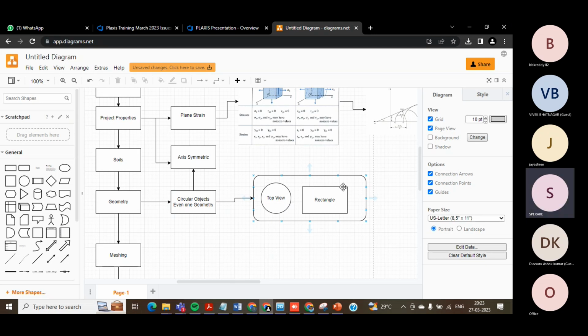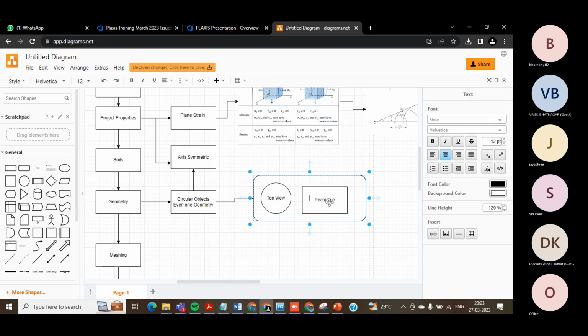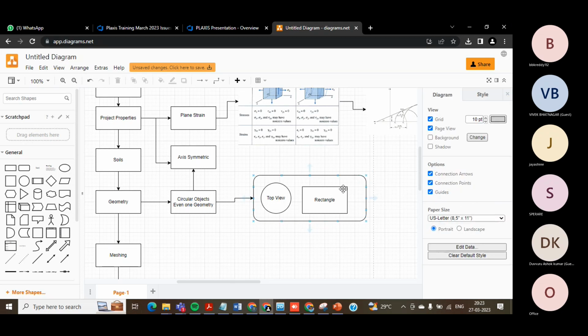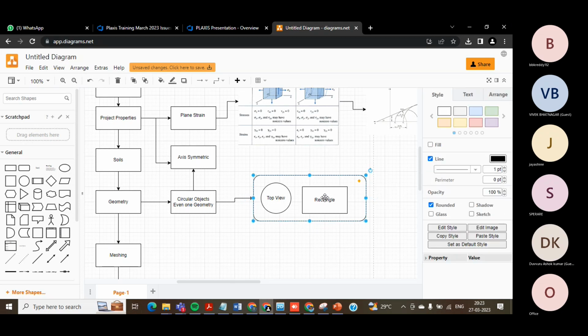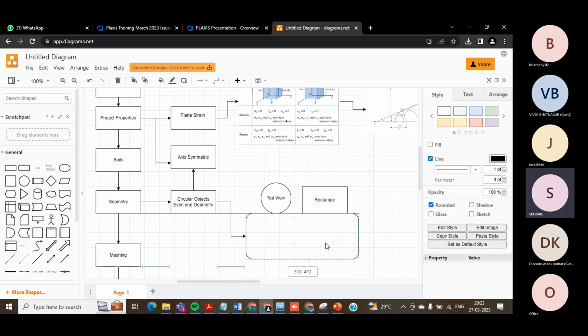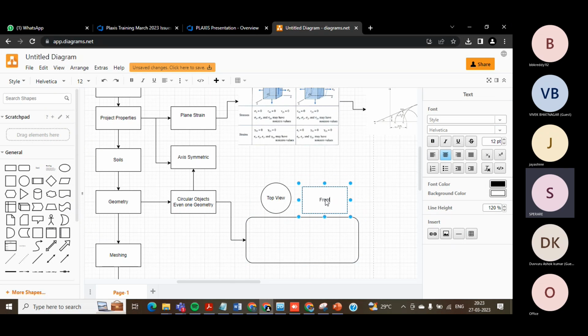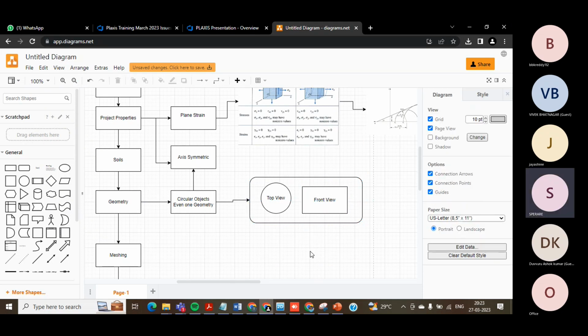and in the front view, you can say this is the front view of this particular object. So this is a circular object: if the geometry looks like this in the top view and the front view, and in all the remaining views like isometric or sectional views, you can easily identify whether it is a circular object or not.